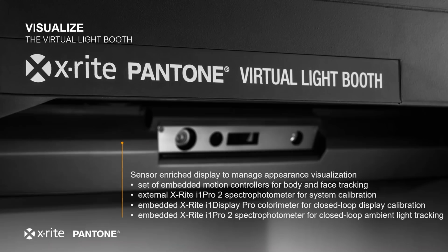We do some kind of sophisticated color management on this device. Not only are we profiling the entire monitor, but we're profiling the monitor according to where your eyes are. And so we're using face tracking to enable us to determine the viewing direction. And then the profile is built for every pixel on the screen, has a different conversion to enable you to get accurate colors no matter which direction you're looking at it from.